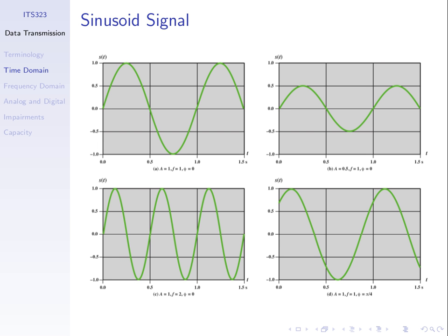And the phase? It's given here, and the phase, we'll explain that when we cover a signal with a different phase. The phase is zero in this case. The phase is the shift of the signal relative to some origin point. Think of a sine wave. When time is zero, the signal amplitude should be zero, with zero phase.